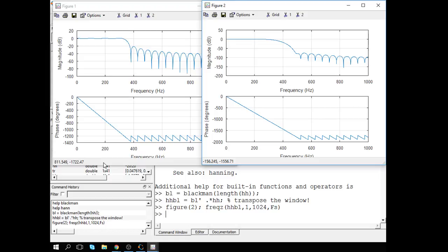That will be quite a nice filter already for audio, for example. You have something like 70 dB stop band attenuation, which is 12 bits, right? 12 bits of signal to quantization noise ratio. Okay, good. And that was just a low pass filter.